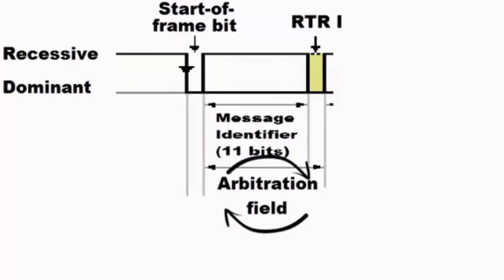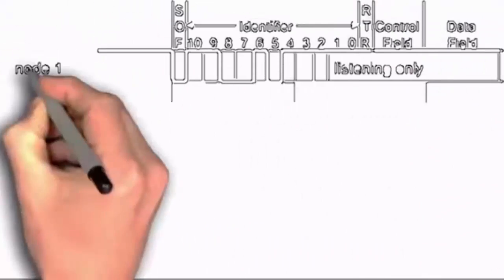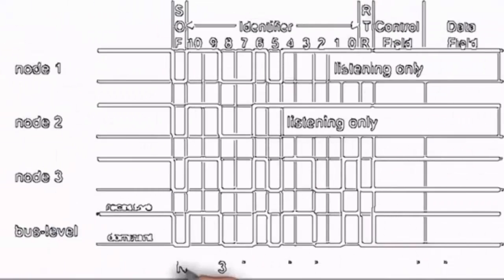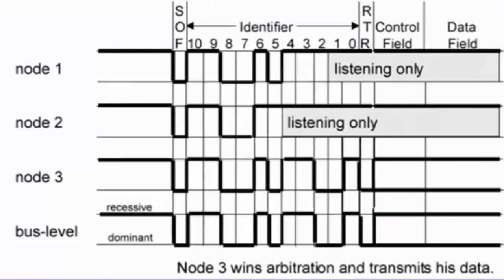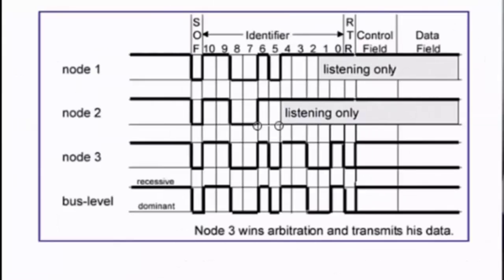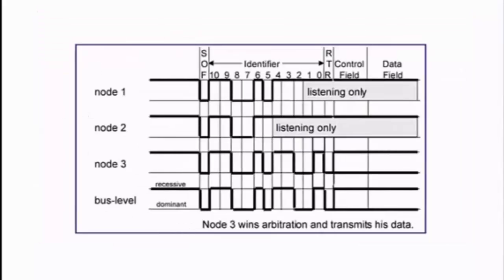This is pretty cool stuff, guys, and it works really well with very little to no crashes, as all the messages stay in a listening mode until at such times that the bus is clear of any higher ranking messages. No messages are lost, as they just wait until the time is ready for their turn to ride the bus and deliver the message. We can see here we have 3 typical messages that have been sent on the bus at the same time. So arbitration starts.